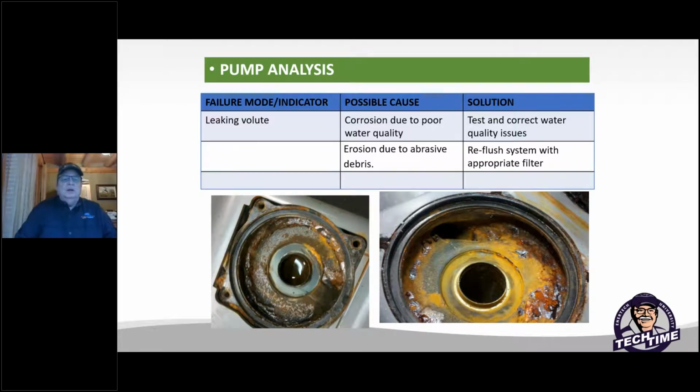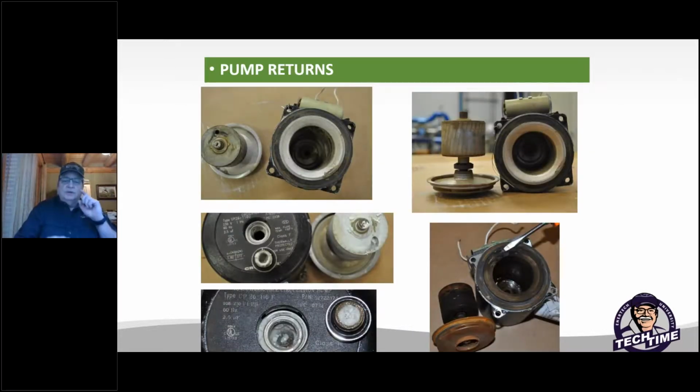Some pump returns that have come in, you can see the differences in the colors. Different things happen depending on your water quality and stuff that you have. And so it's very good for you guys to know there are problems that you have seen. Some stuff I've never seen was some kind of white powdery stuff making kind of like a jelly inside the system. So water in our whole country, in our whole world is different everywhere we go. Testing is imperative. You may think you know how good the water is there, but testing is an approved method in a way that should be good.